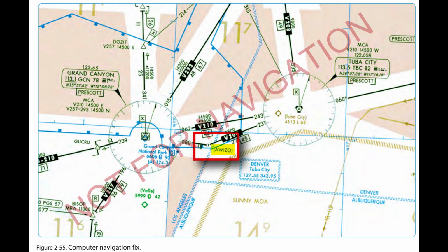Many of the RNAV systems available today make it all too easy to forget that en route charts are still required and necessary for flight. As important as databases are, they really are on board the aircraft to provide navigation guidance and situational awareness, SA. They are not intended as a substitute for paper charts. When flying with GPS, FMS, or planning a flight with a computer, it is critical to understand the limitations of the system you are using, for example, incomplete information, unloadable procedures, complex procedures, and database storage limitations.